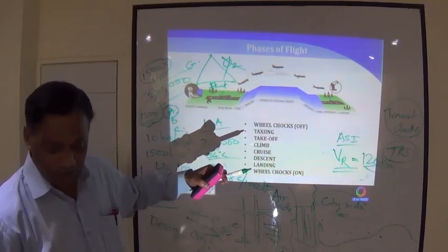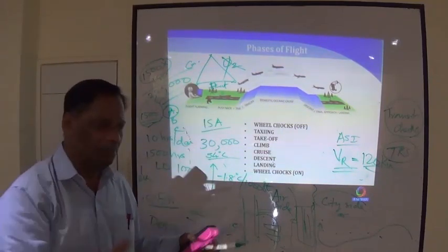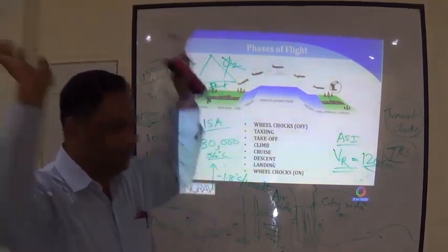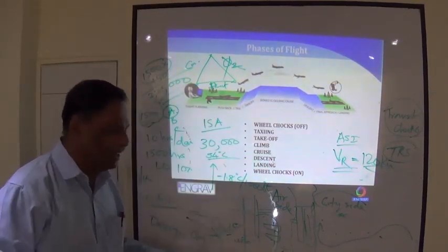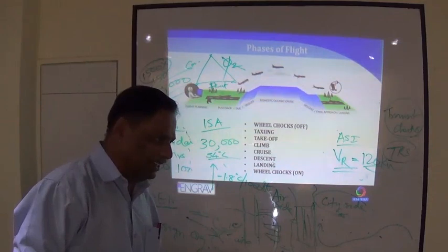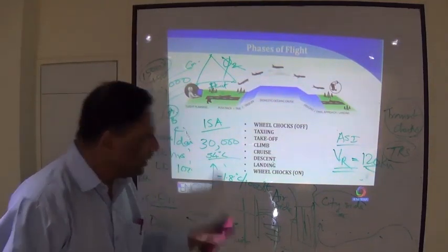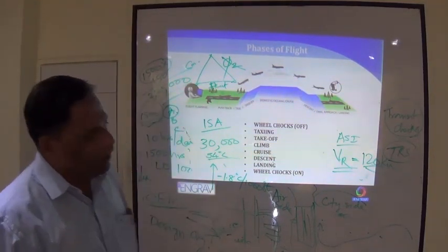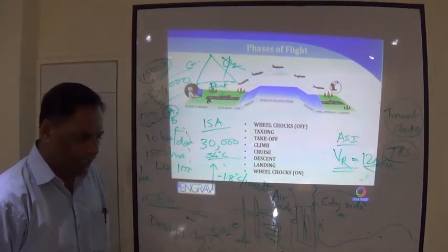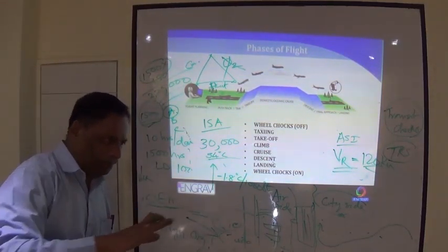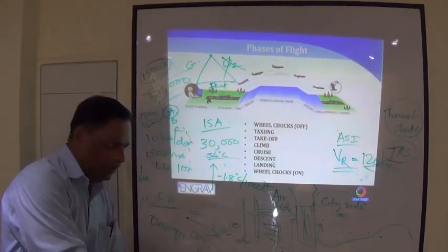The sparks could start a fire. So to avoid that, he touched down on the left and rolled as much as possible on it. At an appropriate time he put the nose down also, so he got two supports.